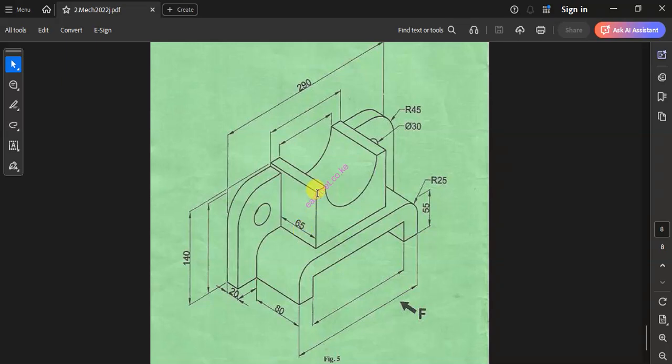The next side is this particular curved area. So again, the dimensions are not being given, but what we know is that the distance from this point to the top point should be, the distance from this point to this point should be 140 minus 55. So we get 85. So it means that the distance from here to here is 85. So we have a height of 85. Then we can assume a length of 100. Let's start with 100.